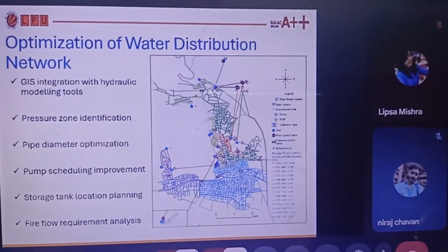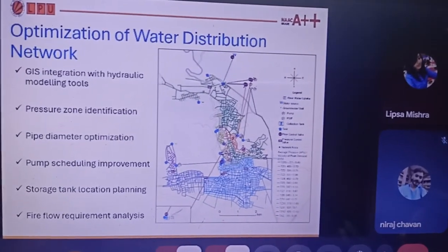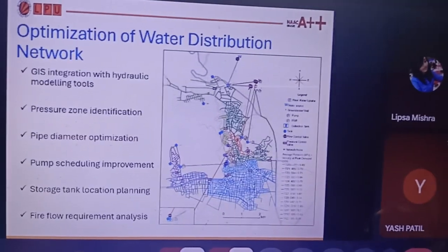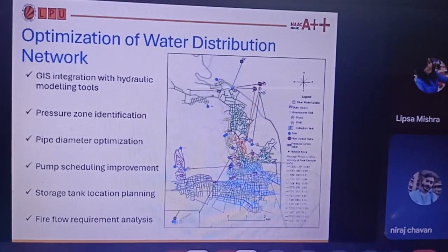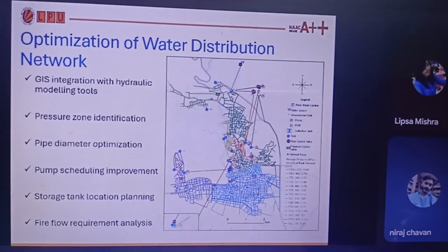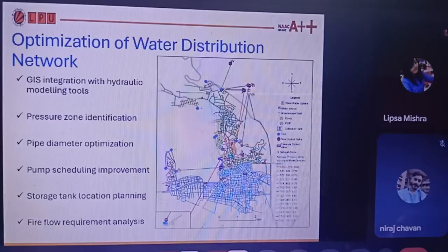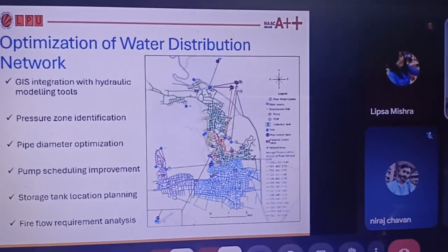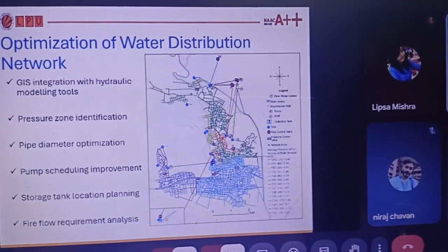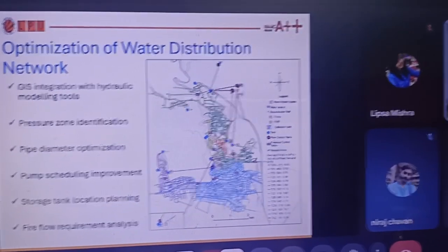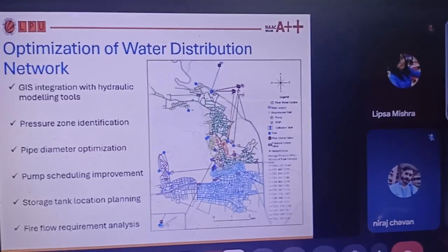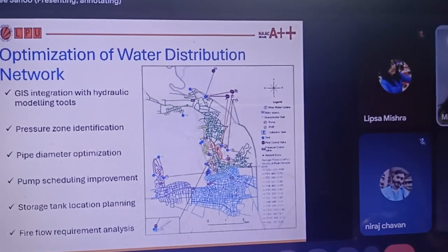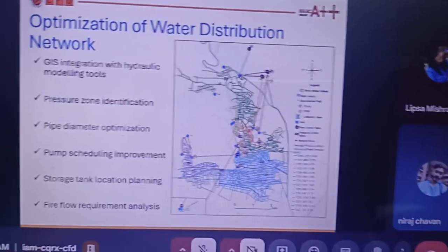In addition to that, volume should be perfect. If it does not flow properly, that means velocity should be perfect. If there is any kind of sedimentation or if any kind of precipitation happens, that means yes, friction factor, which you heard about earlier. So friction factor is also focused here, because if there is friction, you know, energy will be reduced. Which energy? Again, water energy, energy inside the water. So water is moving with a momentum inside it. If momentum is reduced, then obviously velocity will be low, and ultimately you are not getting the water with that much pressure which you require.